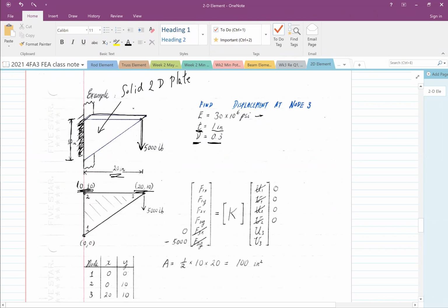The next step, because it's going to be messy. I know what I taught you before is look for the K matrix, the stiffness matrix, then look for the displacement vector. But sometimes it's easier to visualize the problem by defining the displacement vector and the force vector, because I can totally understand the problem and I can reduce the matrix beforehand.